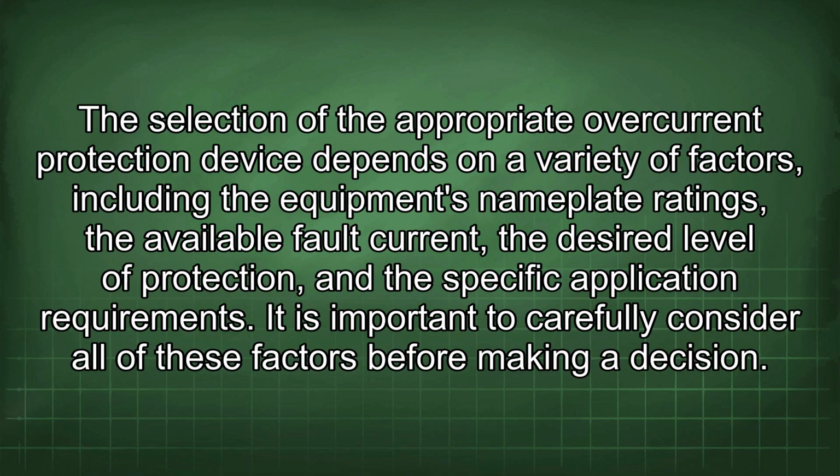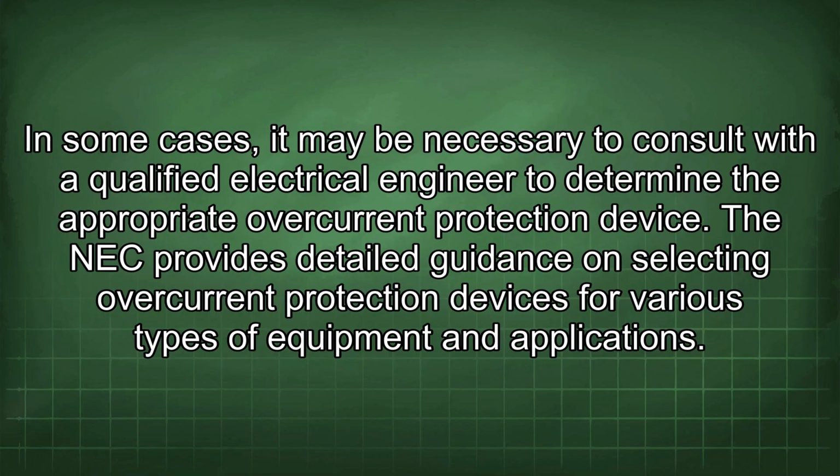The selection of the appropriate overcurrent protection device depends on a variety of factors, including the equipment's nameplate ratings, the available fault current, the desired level of protection, and the specific application requirements. It is important to carefully consider all of these factors before making a decision. In some cases, it may be necessary to consult with a qualified electrical engineer to determine the appropriate overcurrent protection device. The NEC provides detailed guidance on selecting overcurrent protection devices for various types of equipment and applications.